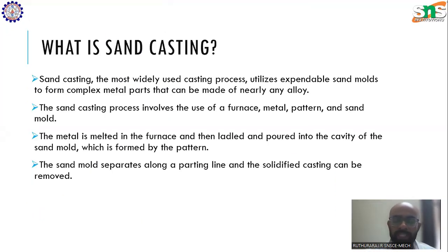There are various types of castings available, namely sand casting, pressure die casting, centrifugal casting. Then there is ceramic casting. So various types of casting are available. But the predominant, most preferred type is sand casting. The reason we are using sand casting is because sand is readily available and sand can be easily reused. Sand is cheap, sand is easily available, sand can be reused again and again.